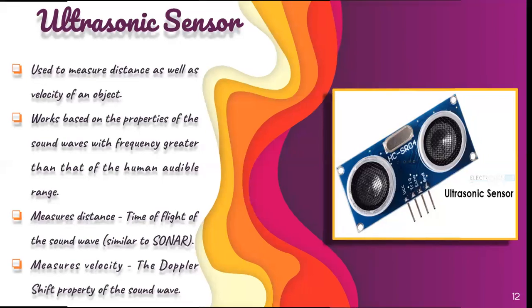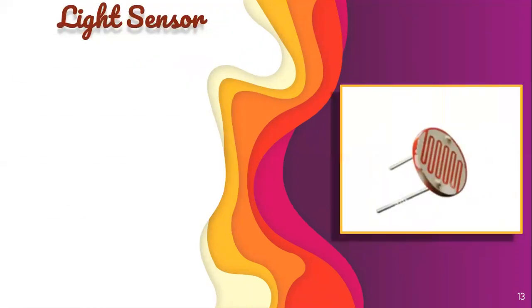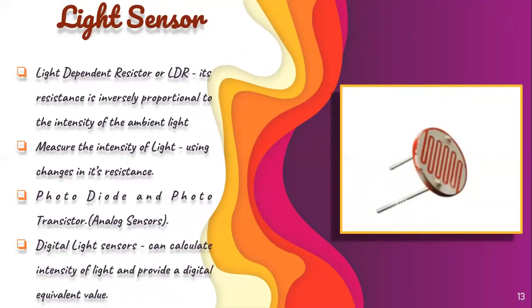Next, we're going to see about light sensor. A light sensor is a photoelectric device that converts light energy, photons, detected to the electrical energy, electrons. There are three different types of light sensors. First is photoresistors. A high resistance semiconductor material called cadmium sulfide cells, highly sensitive to the visible and the near infrared light, is made into this resistor.